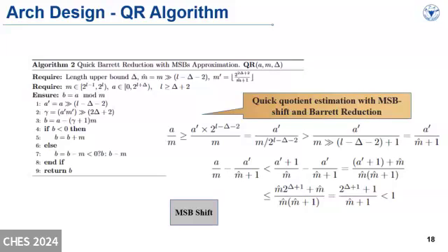First, we have observed that although the remainder in the division equally depends on each bit of the two input numbers, the quotient of the division almost depends on the most significant bits of the two input numbers. As a result, we can estimate the quotient with a small division between their most significant bits.